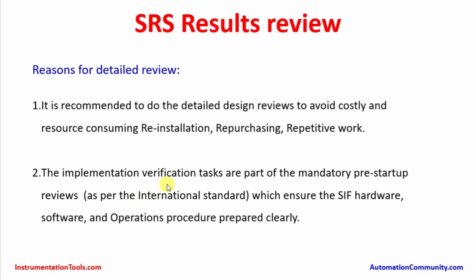Implementation verification tasks are part of the mandatory pre-startup reviews as per the international standard, which ensure that SIF hardware, software and operation procedures are prepared clearly. For each instrument and equipment, there will be one startup procedure. Again, it depends on the company's standards and policies. So this is an international standard requirement.